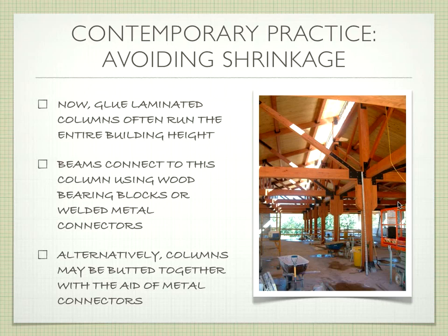Okay, the nice thing is we move into the contemporary world, our world, and we have things like the glulam that we talked about. We have all those engineered lumber products. Primarily in heavy timber frame, we're going to be dealing with glulam. That's the primary method. So we can make pieces that are long enough to span the distances that we need. No longer do we have to cut down the giant tree to make the piece of lumber big enough for what we need. We can make it up in smaller pieces.